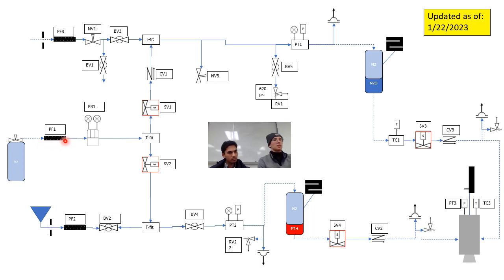Great. So what you're looking at here, we'll be describing each of these, hopefully not in too much detail, but that's particulate filter 1. The purpose of that is as we're filling this whole system, there's a risk that as you plug something in, you capture something in the atmosphere, some particulate, or something comes out of the bottles that are pressurized that goes into the feed system, and those particulates eventually cause problems in the nitrous oxide system. We're worried about a strike of a particulate against the wall, which is literally like lighting a match, causing a spark, which could decompose nitrous oxide.